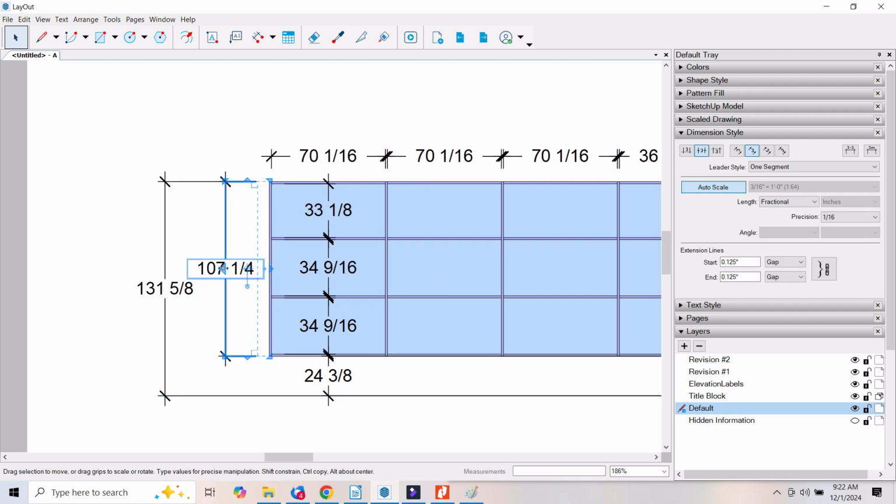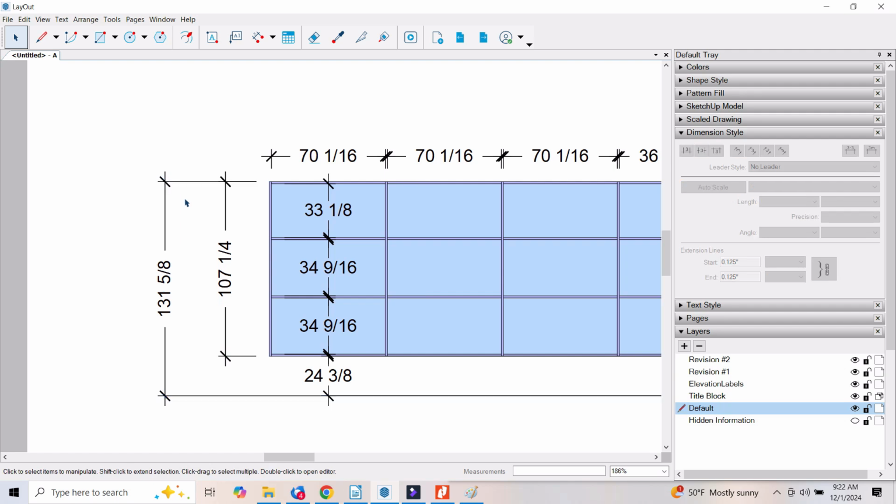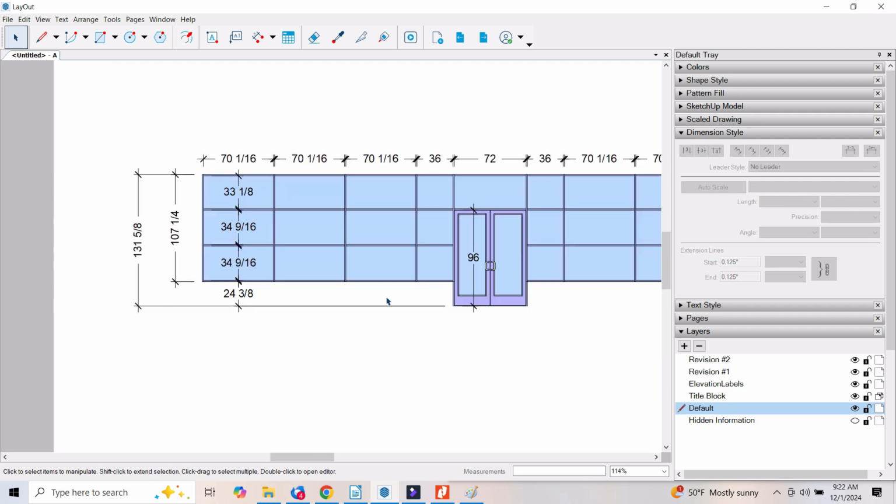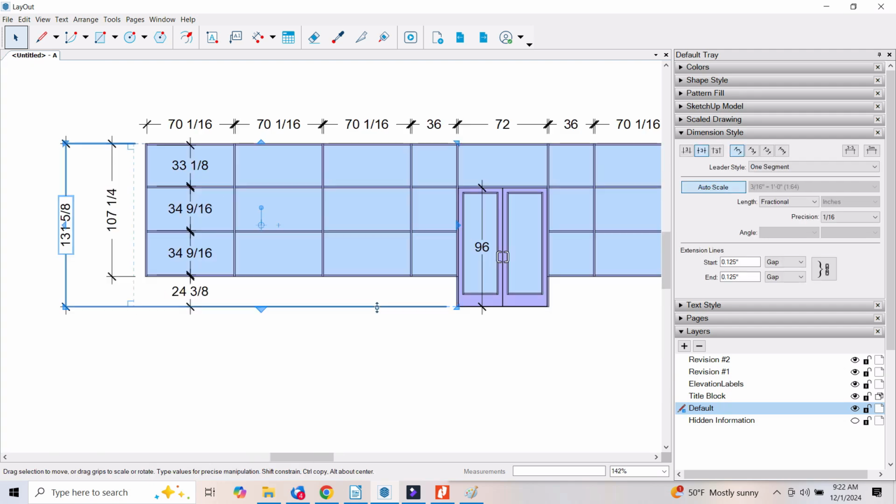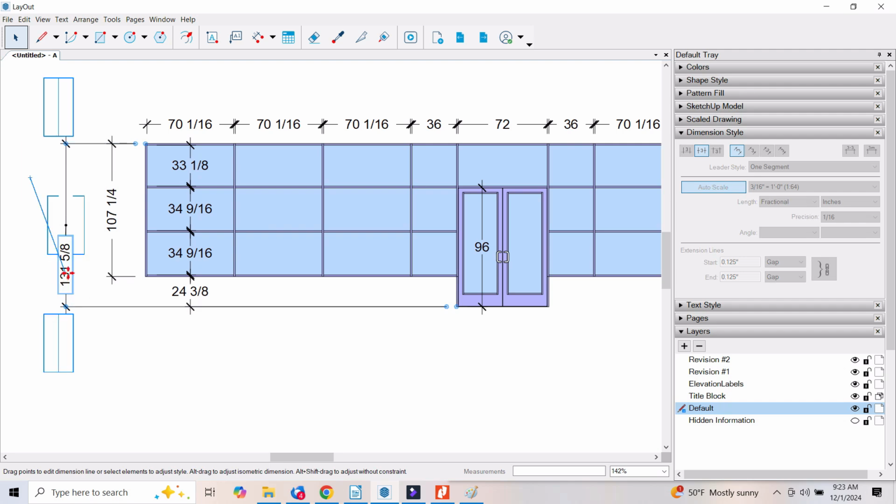Sometimes we don't have all the space that we want to have, so we could change the dimensions, write them vertically. While we're looking at this in the dimension tool, we may want to change the way that it displays. The way you could do that, you double click on the dimension grouping. You can grab the number value and move it, so you're not constrained to where that appears.